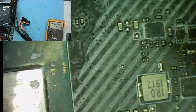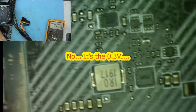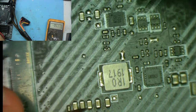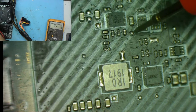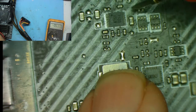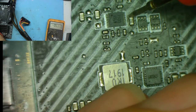So these capacitors are on the output of this, and that's the one that's 0.7 and should be 1. This will probably be the input capacitor on the other side. Does that go to one of these coils? First we've got to find out which end isn't ground. This end will probably be ground. This will be on the input voltage. Input capacitor, regulator, output capacitors, yeah? But we can check from the chip, which we will do.